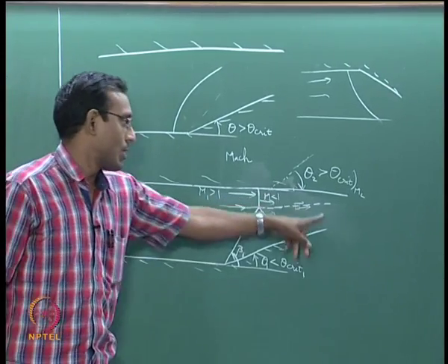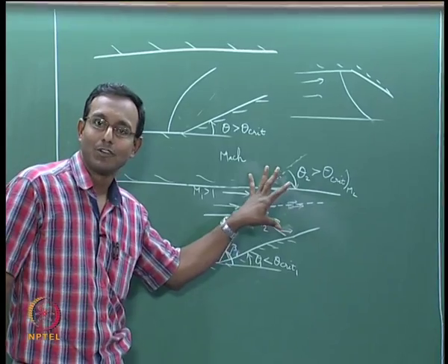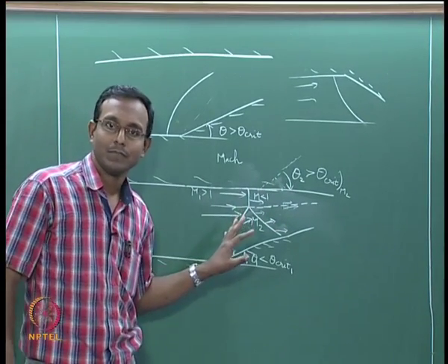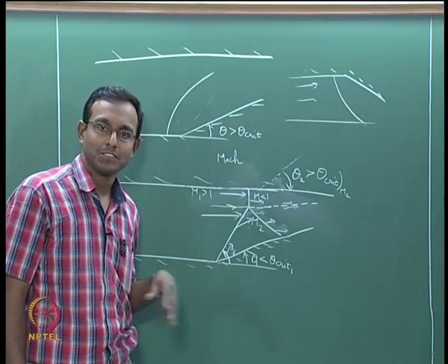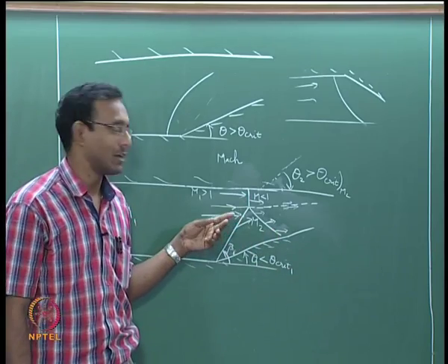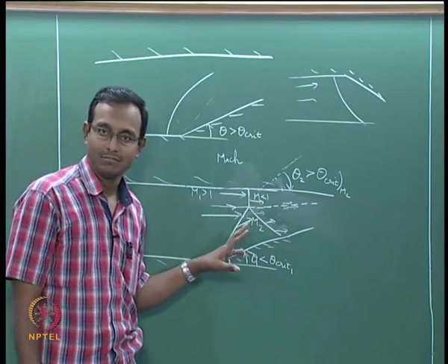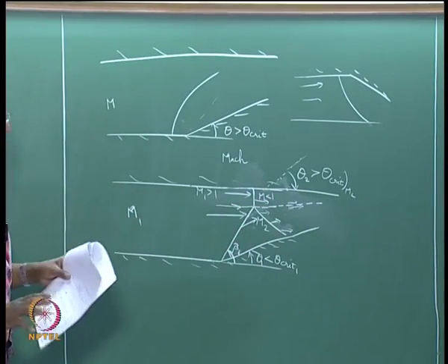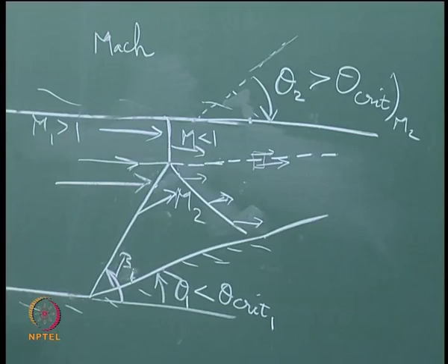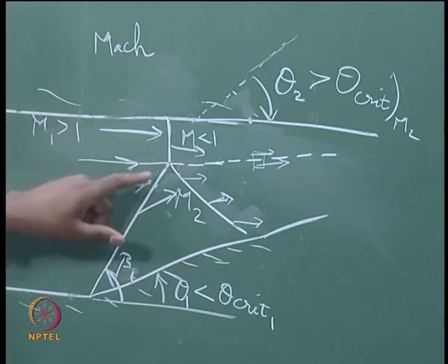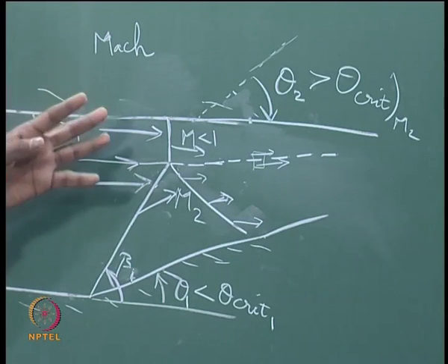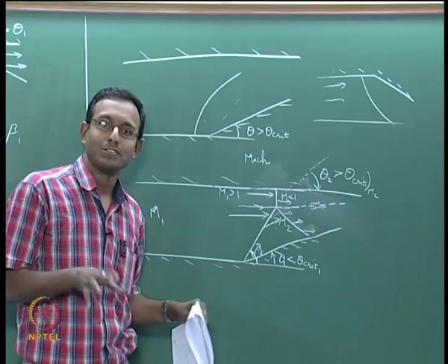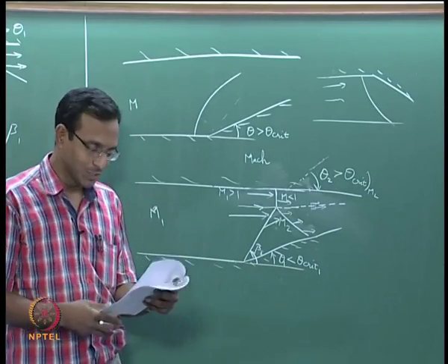Now, overall I am showing you all this, but this particular problem is very difficult to solve from our gas dynamics. If I go and simulate it, I cannot get analytical solutions for this. If I simulate it in some CFD programs or numerical algorithms, I can solve this problem exactly and I will get some nice solution for it. But I cannot give you an expression saying for this much height it will be a normal shock, after that the shock will start curving like a bow shock. I cannot tell that from here because, similar to a bow shock, for all the same reasons, it has transonic region, subsonic region, supersonic region, everything together, it becomes a more complex problem to solve and we will not solve that right now.